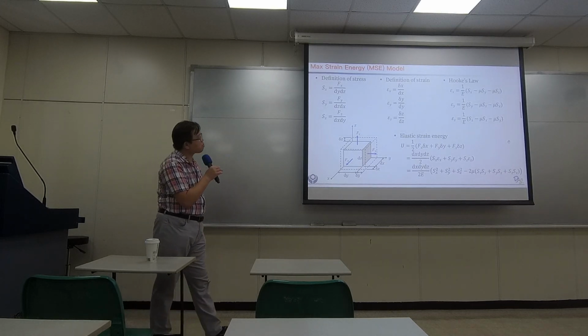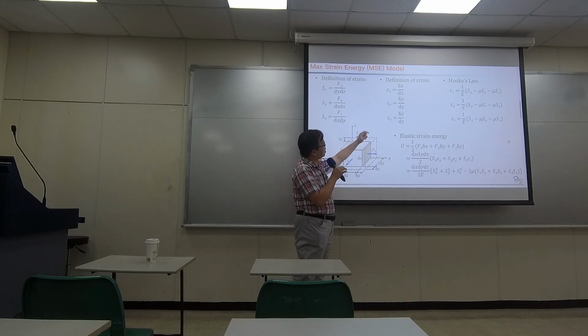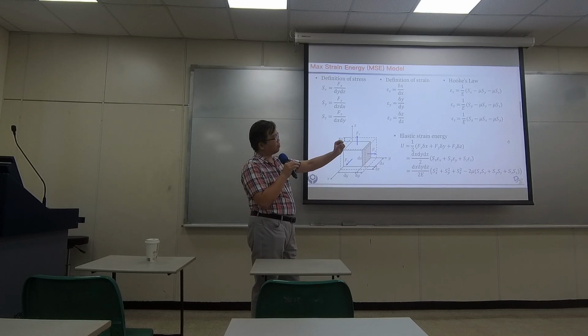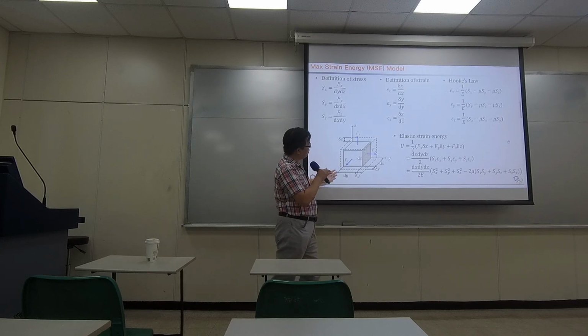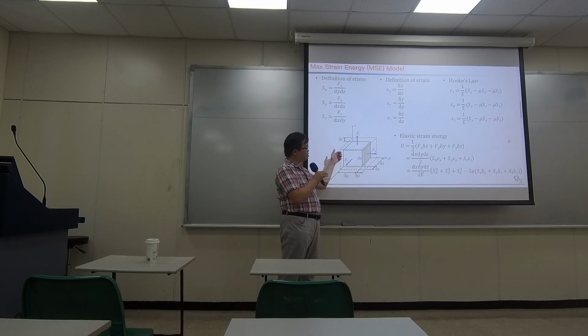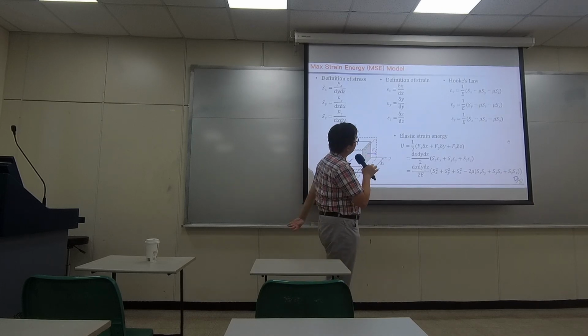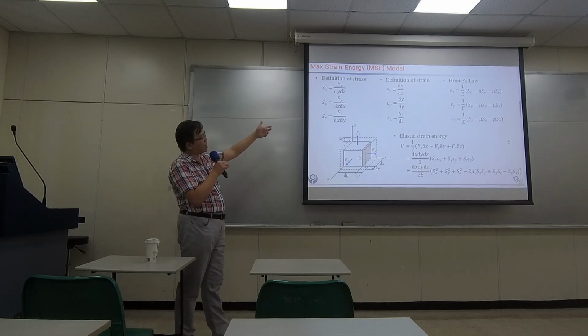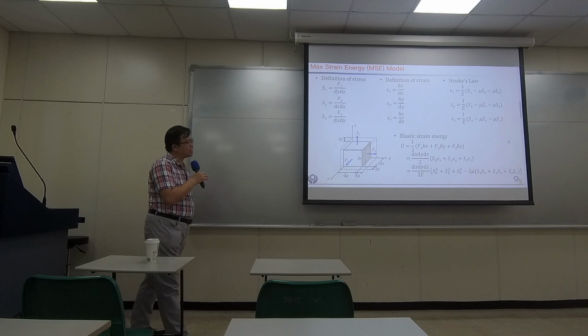That's quite simple. Now, let's go to the definition of strain. Strain is the ratio of the deformation over its original length. By definition, all the deltas are the deformations along each direction, and all the d's are the original lengths. So I can easily compute the strain along each direction. The first one is delta x over dx. That gives you the strain along the x direction. Similarly, you have the second and the third equation.